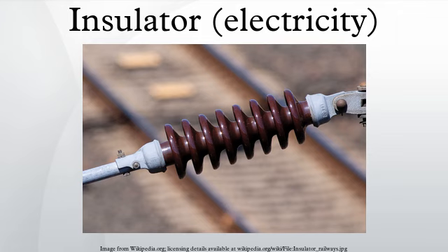Each unit is constructed of a ceramic or glass disc with a metal cap and pin cemented to opposite sides. In order to make defective units obvious, glass units are designed with Class B construction, so that an overvoltage causes a puncture arc through the glass instead of a flashover. The glass is heat-treated so it shatters, making the damaged unit visible. However, the mechanical strength of the unit is unchanged, so the insulator string stays together.